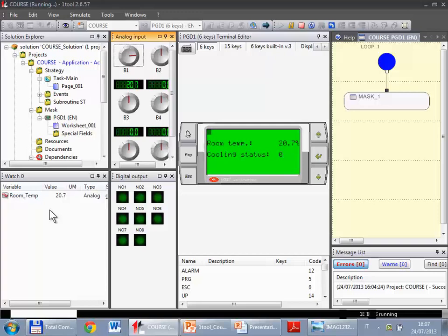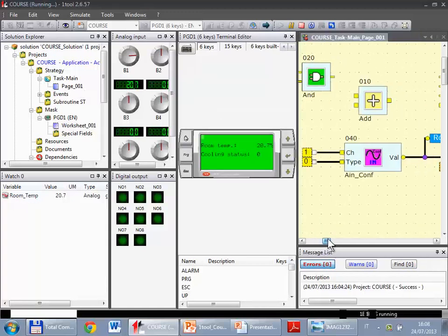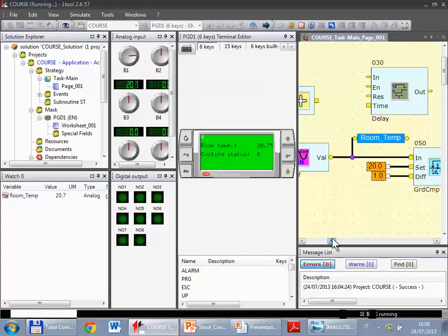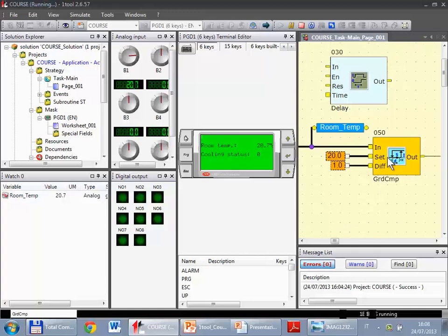Another thing is that you can open the page part of the project. So double click, for example, strategy page, the system opens here, the strategy page here is. What is the advantage to have the strategy page? First of all, notice that in simulation, all project is read-only. So here you can't move, double click to edit, delete, and so on. Everything is read-only. So the advantage is that you can see how the project works.